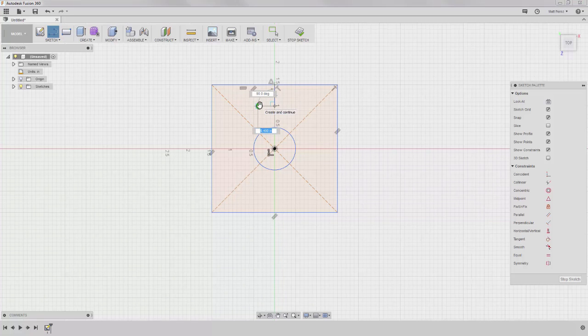For this lesson, we want to drag the line to the right until it intersects with the construction line, making sure that it's horizontal. Next, we will click on the last point, hold down the left mouse button, and drag down and to the right. This motion will begin to generate a tangent arc. Drag the arc down until it connects with the vertical line on the right and is tangent to it. After releasing the left mouse button, press the Escape key to finish the Line tool.